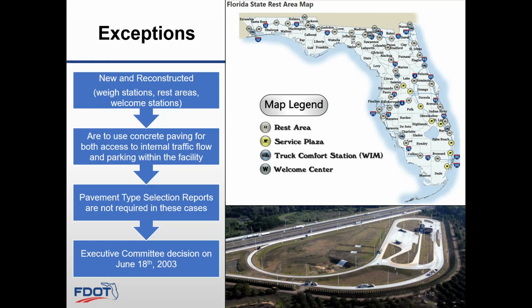Some other exceptions. By Executive Committee decision on June 18, 2003, all new and reconstructed weigh stations, rest areas, and welcome stations are to use concrete pavement for both access to internal traffic flow and parking within the facility. So a pavement type selection report is not required.